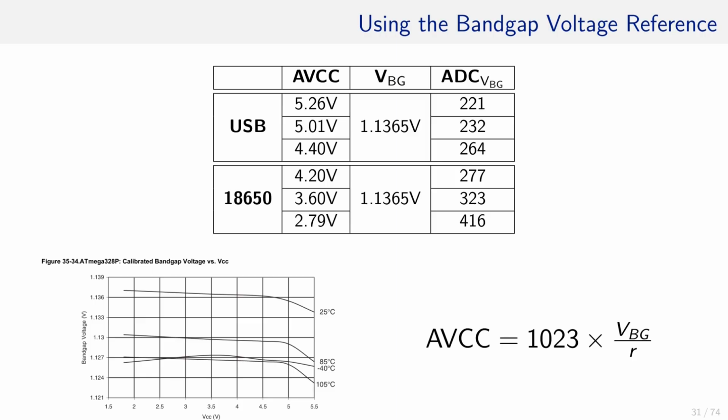As you can see, the higher the reading, the less juice is in the battery. I do not even have to do the calculations below in the formula. In the program, the ADC value can be read, and any value above a threshold of, let's say, 400 will trigger some event preserving battery or asking for a replacement.